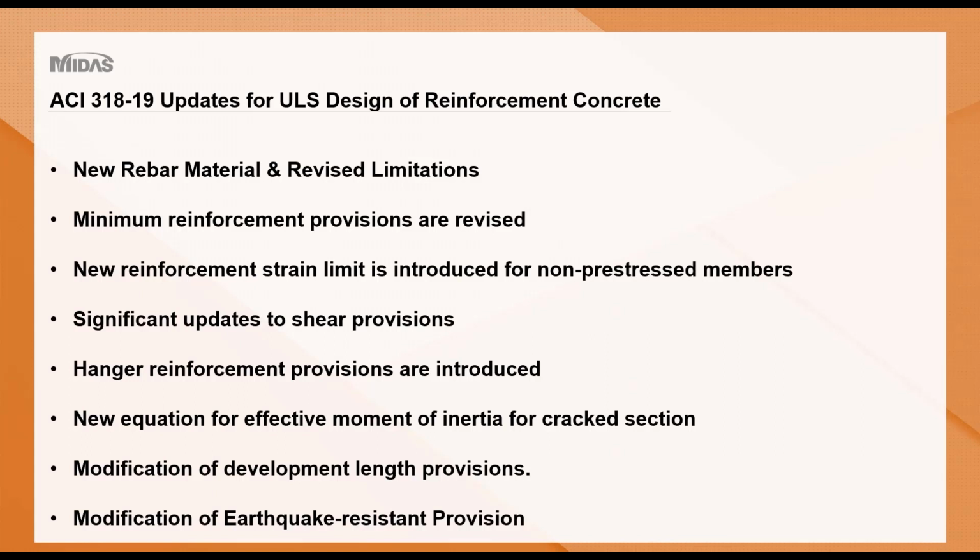2. Minimum reinforcement provisions are revised. The minimum flexural reinforcement regulations according to the reinforcement type and grade were integrated into one. 3. New reinforcement strain limit is introduced for non-prestressed members. This is a new definition of epsilon T associated with the tension-controlled limit.